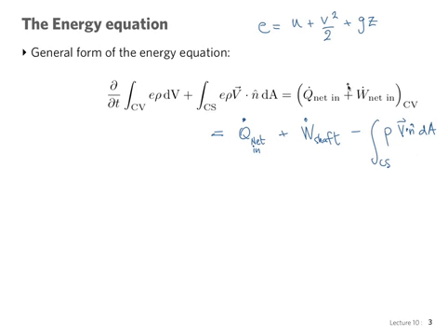So what we can do now is, for fluid systems, we know that often in mechanical engineering systems, what we will have is precisely a fluid interacting with rotating machinery. And so we'll take the pressure work to the other side of the equation and put it together with this integral that has the control surfaces already. And you see, we can write the full term-by-term expression of the energy, and then the equation becomes a little bit more adaptable to our situations in fluid systems.